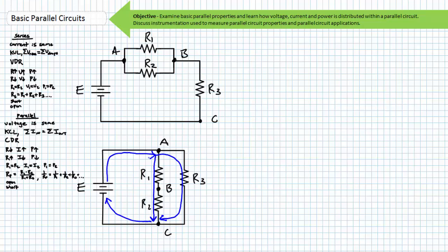In this circuit, flowing source current enters node A and has a choice to travel through two paths. These two paths are clearly in parallel with one another. One of the paths is just R3. However, the left path has R1 and R2 clearly in series with one another.